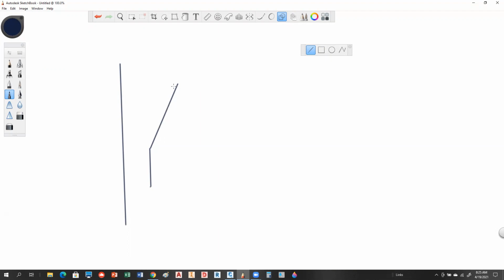And what we're actually going to do is have it follow this alignment right here, but it's going to target this back here. So you're going to have two targets. We're going to target the alignment, which is just the horizontal information to make it widen, and then it's going to target the profile so that as it generates stuff, it's going to know what's going on in terms of how it's targeting.